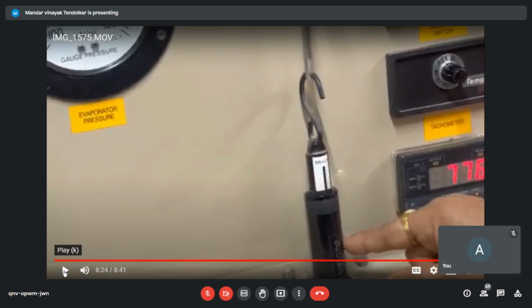Okay, so the spring balance gives me the reading of the force which is acting on the piston shaft into the displacement. That will give me the work, and motor RPM known, so I know the time factor. So this force, work per unit time, that will give me power. Is it fine? Any doubt to anyone? No, sir.